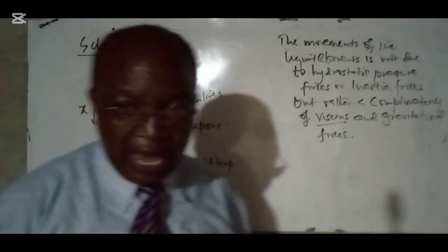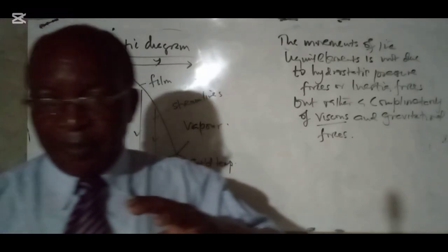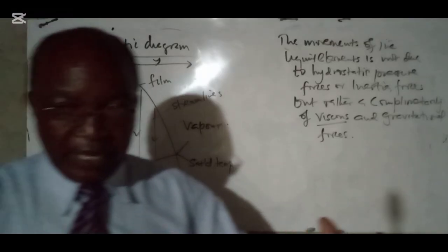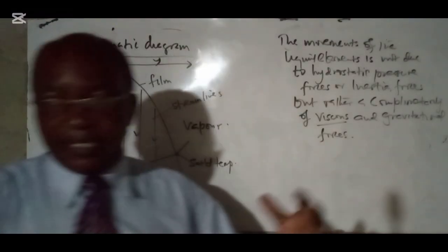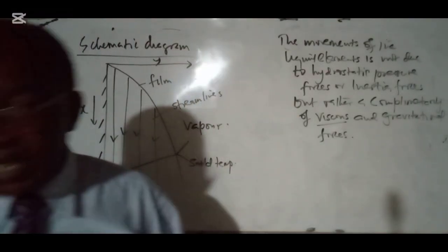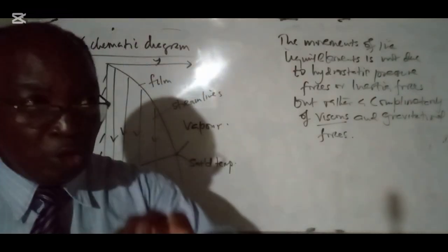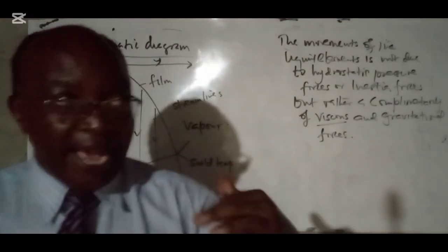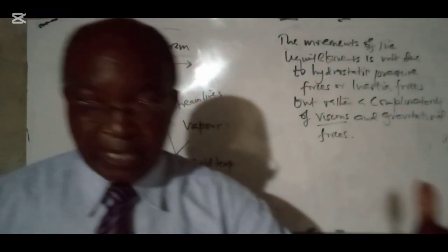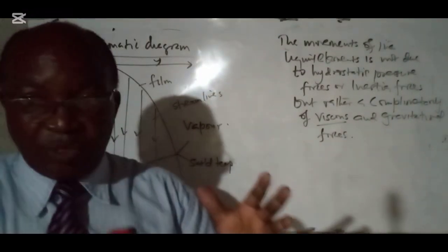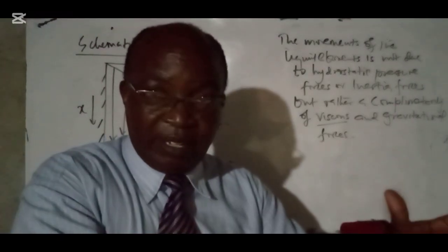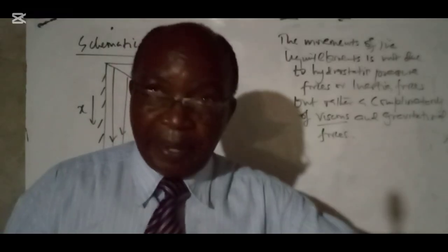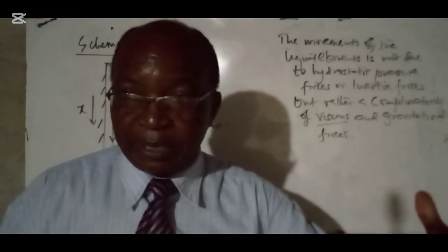Now, we know that is the case, because remember there will be no temperature difference at the condensed film surface. There's no temperature difference between the condensed film and the vapor. So we don't expect heat to be transferred from the film surface to the vapor. No, because the temperatures are about the same.